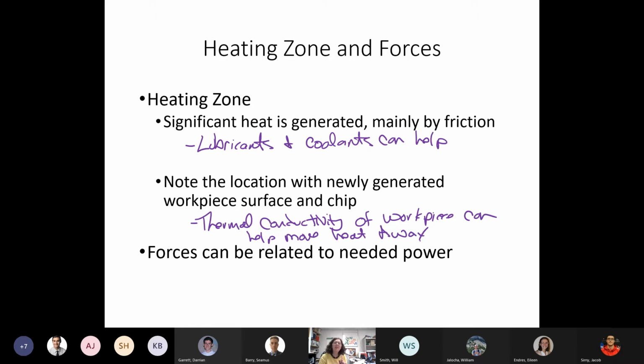So what does this mean for a plastic? Well, when we machine plastics, it's kind of interesting. I find it interesting that because plastics are predominantly thermal insulators, there are some challenges with machining plastics and the increase in temperature. In a metal, we see such high thermal conductivity that thermal energy is generated and it tends to disperse throughout the metal.